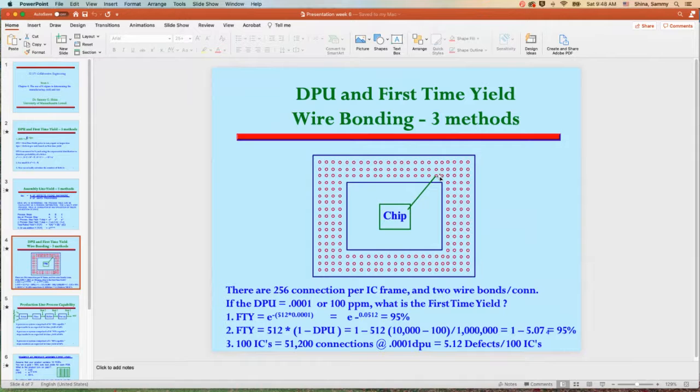Now they have chips where, because the number of pins gets to be so big, they use what's called a ball grid array. Rather than have pins, they have little solder balls at the back, and essentially the whole back is covered with them. This one has 256 connections, but they got into as much as double and triple that.